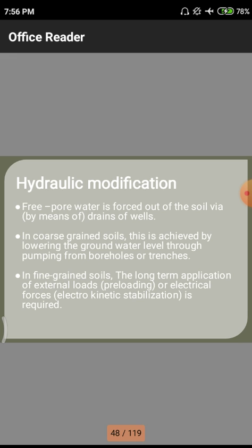So in the primary case itself, we need to remove all the water present on the site, and whatever greenery is present, like waste trees and others. All those we need to remove. After the removal of the total water and whatever vegetation is present in the particular soil or strata, we need to go for our construction works. And some small modification techniques that those soils require will also be done using these different physical mechanisms, rolling mechanisms, and hydraulic mechanisms and others.